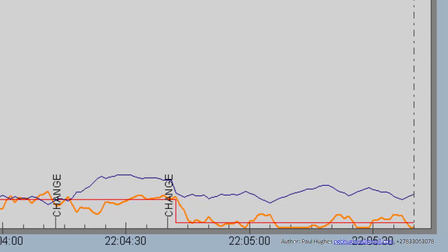What you can see over here is the PV goes to 0 here. The output goes up, and then eventually at some point you've got enough flow through the orifice transmitter that you do get a flow reading, so it starts coming up.